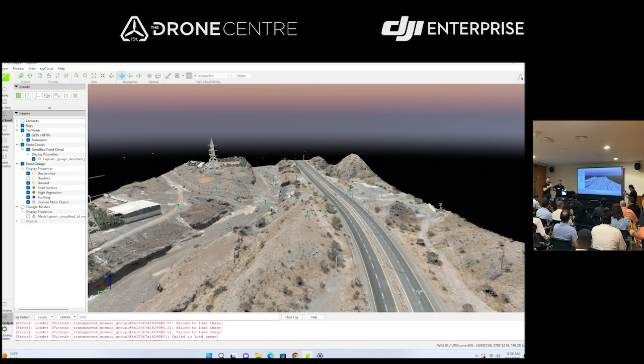That's the biggest issue. Emergency services are typically worse for that, in my experience. As operators here, I'd imagine you'll use more intelligence when operating. But don't use the collision avoidance as the standard when flying near an object. It should just be a safety net. Still operate with caution. Basically, when you're planning a flight, you just have to make sure that you're flying above.